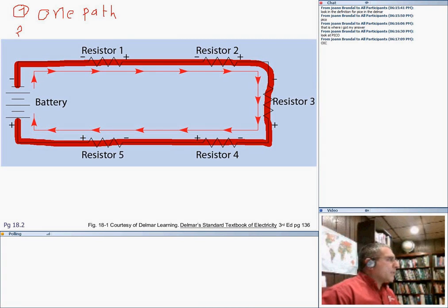Number two about series circuits, and you guys have to memorize and understand this. Otherwise, you will never be able to analyze a series circuit, and when it comes to combination circuits, you get confused even more. Why? Number two, guys, in a series circuit, the voltage here is called V total. The total voltage equals the sum of all the voltages in the system.